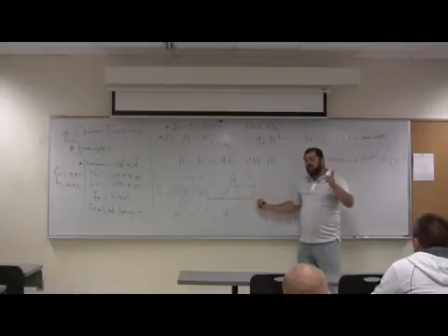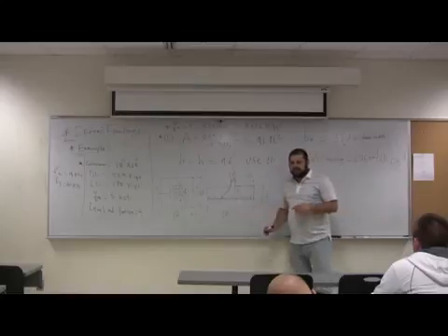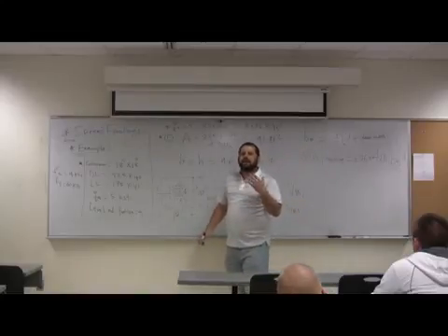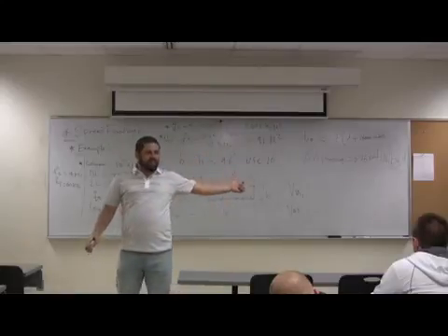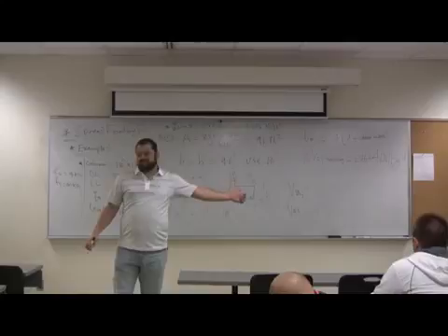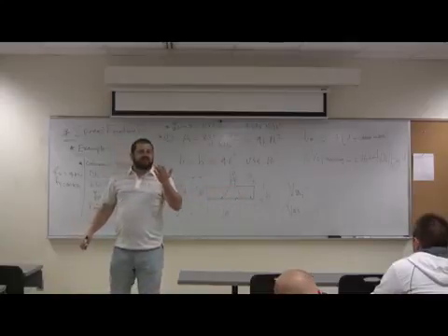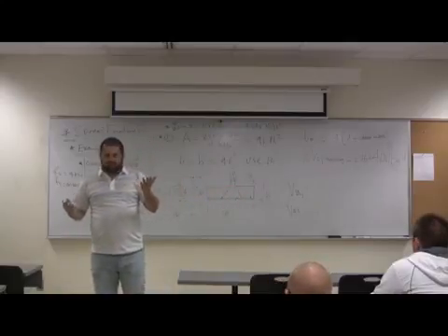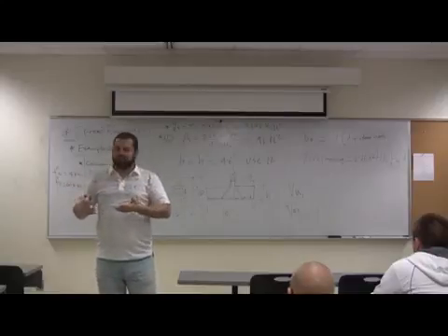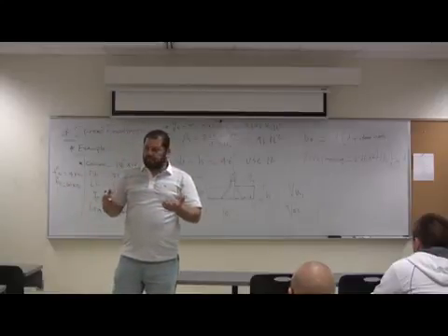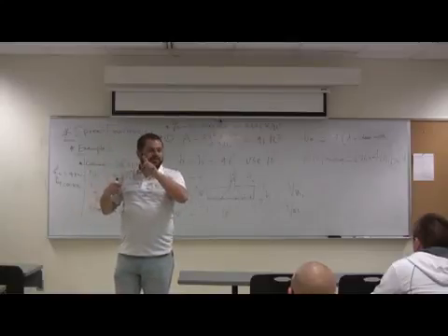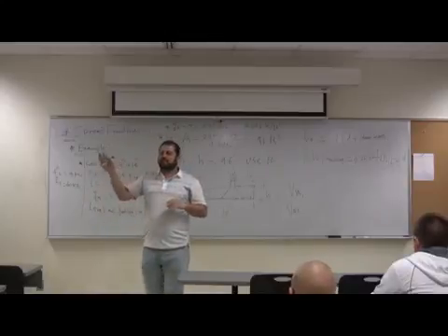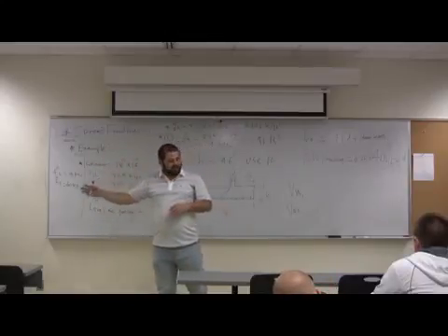So d will be h minus 3 minus the diameter of this bar minus half the diameter of this bar. If you have number 8, then you will have 3 plus 1 plus half. If you have number 4, number 5 or number 6, it's going to be like 4 inch. Assume we use number 6, which is 6/8. That's 6/8 plus 3/8, half of it is about 1 inch. So roughly you can have h minus 4, or h minus 4.5 to be on the safe side.